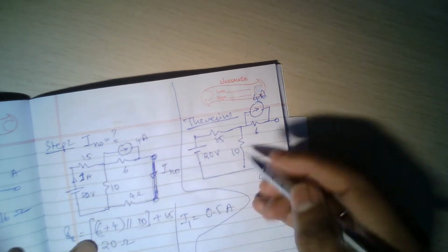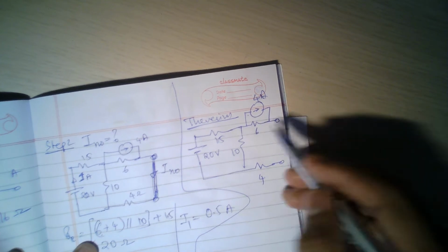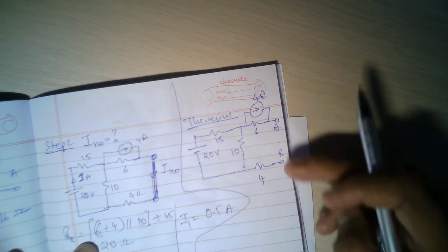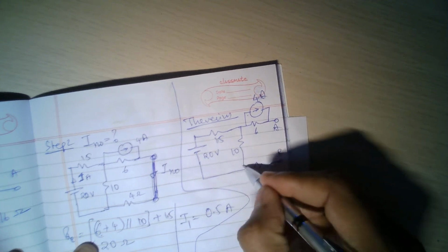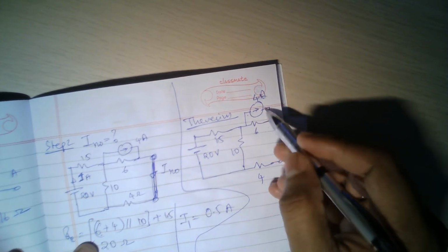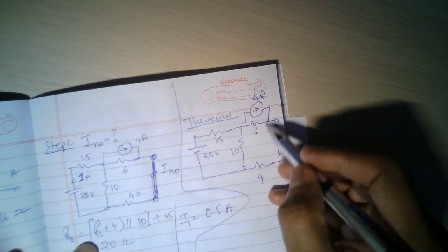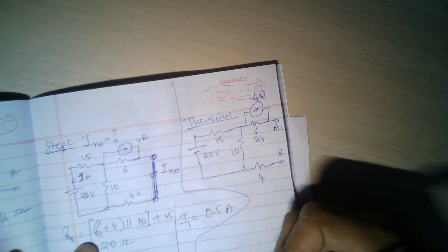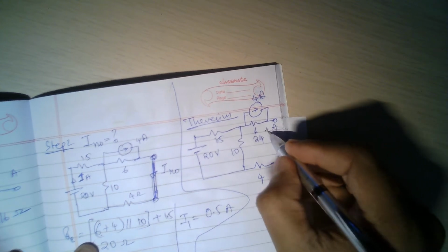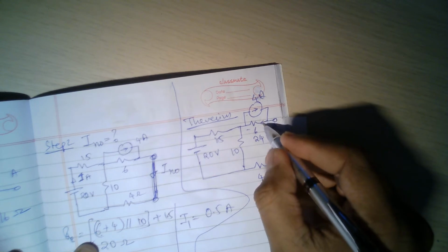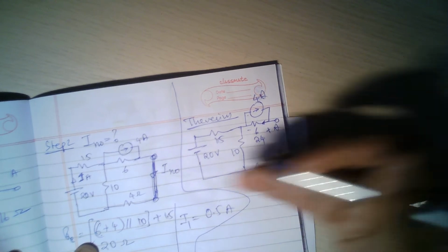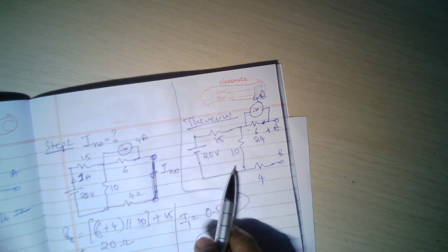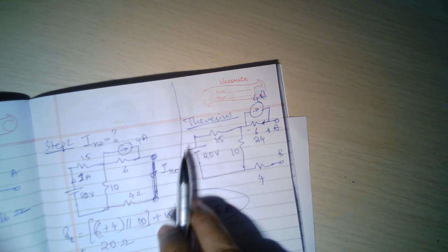Okay, now you see here AB is open circuited, and I want to find the VAB. That means apply KVL from B to A. So this 4 amperes will flow completely in this itself, in the 6 ohm resistance itself. So 24 volts will be the voltage here. Which side will be high voltage? This side will be high voltage, this side will be low voltage, because the current is going in this direction, towards the left. Meanwhile, here 25 ohms is the total resistance in this loop.